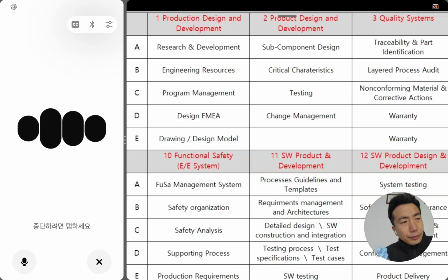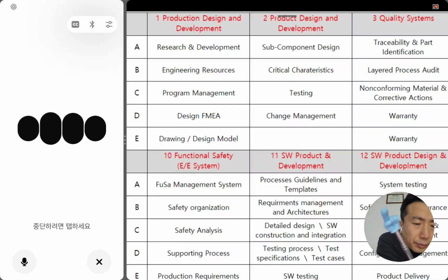What you did well, you clearly showed that DFMEA is done before samples, not after. DFMEA is cross functional. You separate DFMEA into hardware, mechanical, software, optical, which makes perfect sense for an automotive camera. DFMEA is linked to PFMEA. DFMEA is documented and shared via PLM. These are all strong audit signals. Where it drifted, normal, not bad. A few things auditors listen for, but you didn't fully state yet. Who participates, not just we. How risks are evaluated, severity, occurrence, detection. What happens to high-risk items?